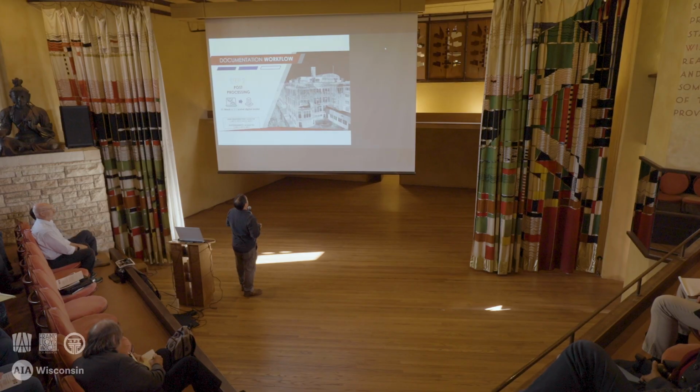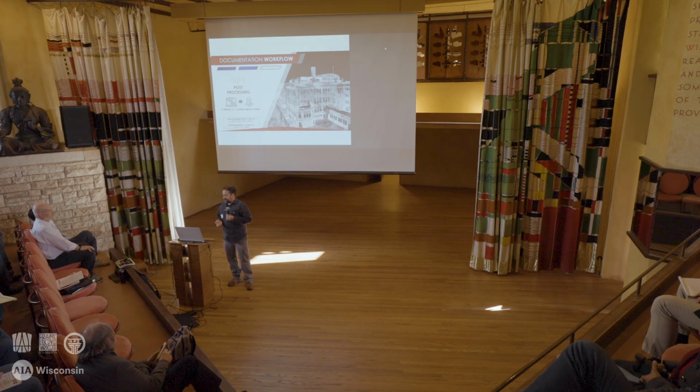But when you look at this and say, what is my project? What do I need to do with this? How soon can I get a Revit model put together so I can start working with it? The beauty with these point clouds is you don't necessarily need your Revit model right away. It doesn't have to be Revit. It could be AutoCAD. With something like this, you can take a slice out, crisp up the point cloud data, and then start drafting, working with your markers, working with your trace, and get through all your schematic design while you've got a team going through all the existing conditions.